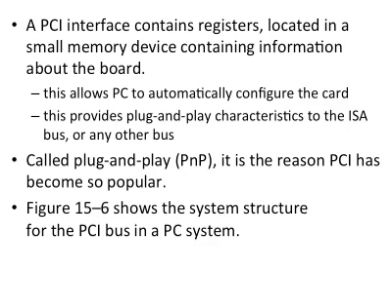A PCI interface, which we'll look at, consists of registers, and these registers are located in a small memory region. The registers in this region contain much important information about the device. By device, we mean, for example, a network interface card or a video card. Many such devices have the PCI or PCIe interface, which is used to connect to the motherboard. That's how you build a system with not only processors and memory, but also many different kinds of devices.